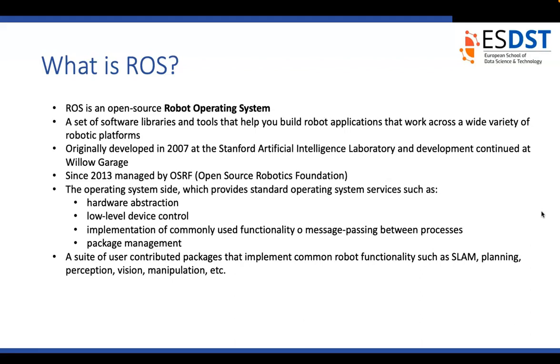So what ROS provides is a high-level abstraction of this hardware. You write generalized controllers, and then you can use your underlying hardware. You can change the hardware, but you do not need to change the software controllers. So when you say a robot is using a ROS controller, that means it has a software controller written that can be used. You just need to change the robot controller on the hardware and it will still work. Okay.